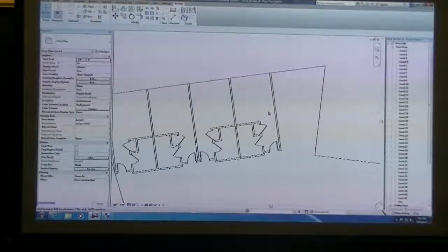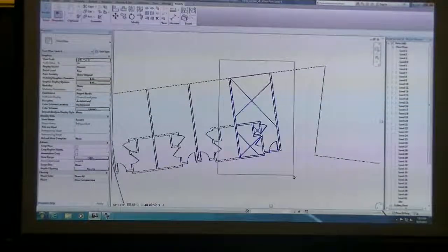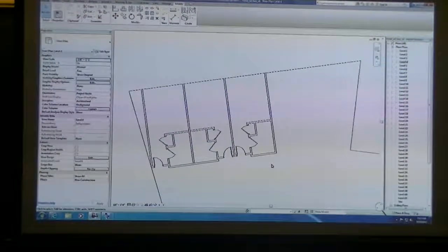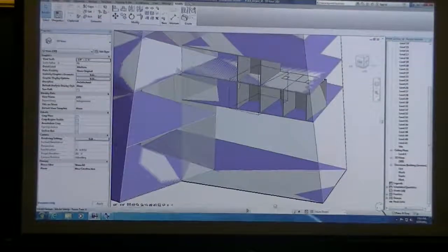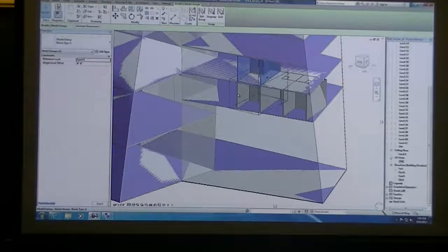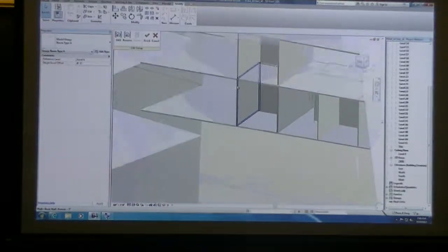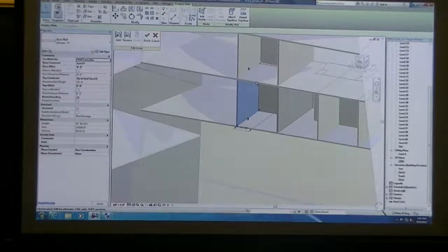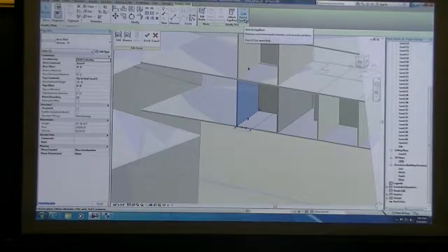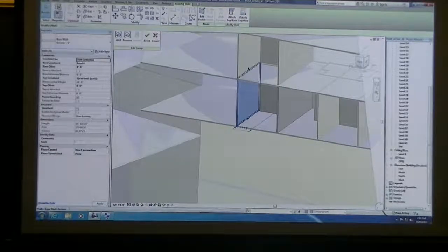So I'm going to go back into this. So you just click on attach top base and then click on the slab? When you click on the wall, if I'm in an edit group, let me click on this. I can click on the wall, you want to use attach, and then the next option will be to select the actual base. Detach would be if later on you decided you want that wall to go back down to being 10 foot or some other dimension, you would just click on the wall and then detach, and that would remove that connection.